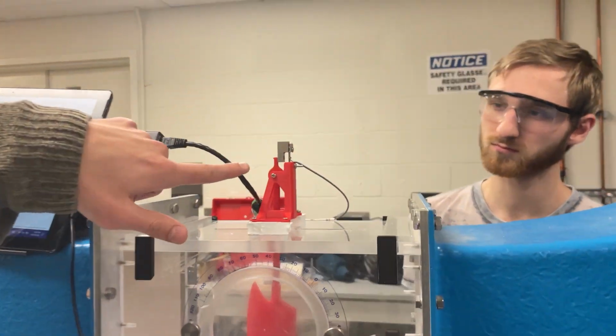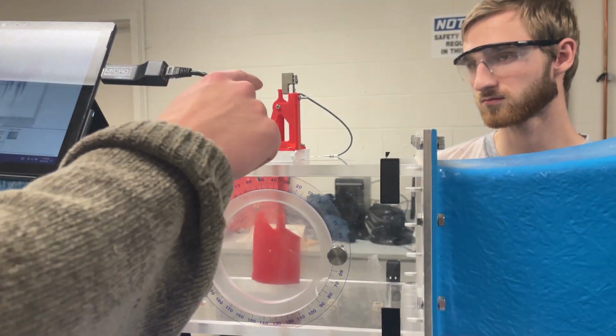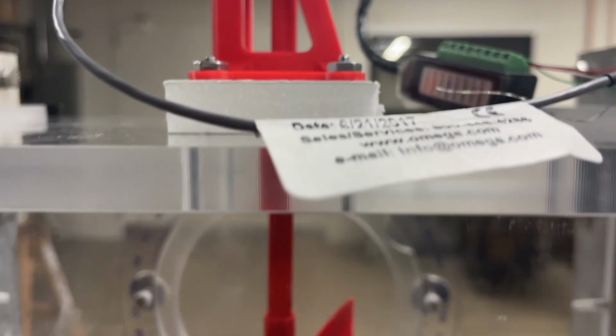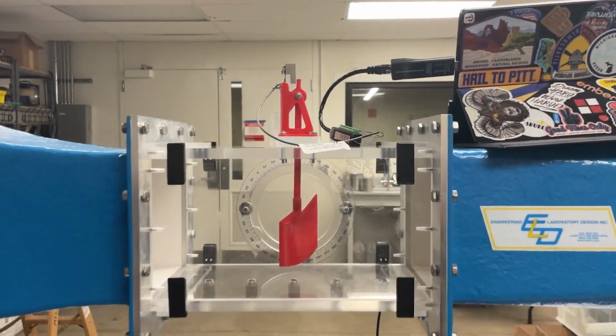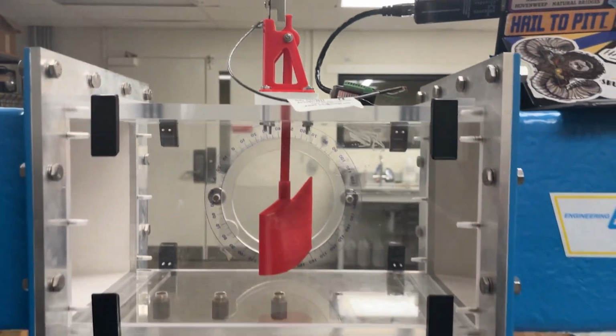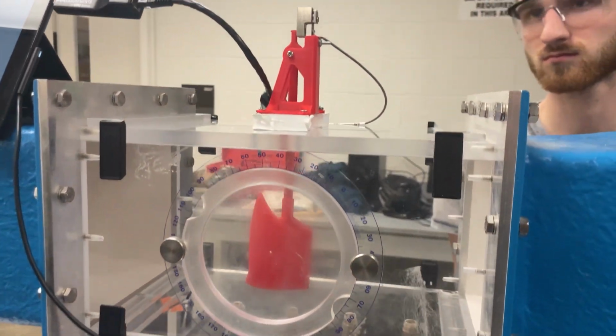So if you zoom in on this, this is how we're measuring the force of drag, and we're actually measuring it indirectly through this lever arm, and that accomplishes two things for us. First, it gets the force sensor out of the wind tunnel so that it doesn't affect our aerodynamic profile. And it also, as the sides of that lever arm are uneven, we get an amplification ratio of about 8.5 for this situation. And that amplification ratio takes the force that is felt by the fin, which is relatively small, and amplifies it to something that the force sensor is more able to read.